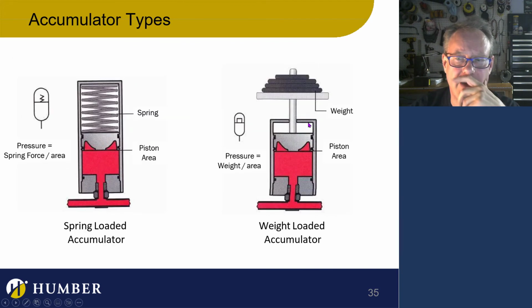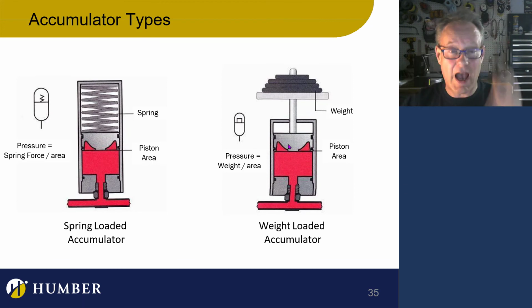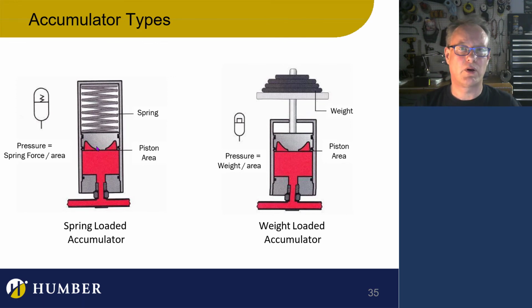I just want to go back to the gravity. This is pretty cool. I like gravity accumulators because they're always going to give the same amount of pressure, no matter how empty or full they are. With springs, as they get smaller or as they get used, their pressure decreases, very much like an accumulator for pneumatics. As the air vents out, it's going to lose pressure. But in this case, the pressure is always the same because it's gravity fed, and gravity is never going to change.